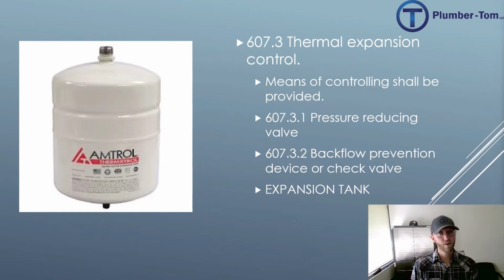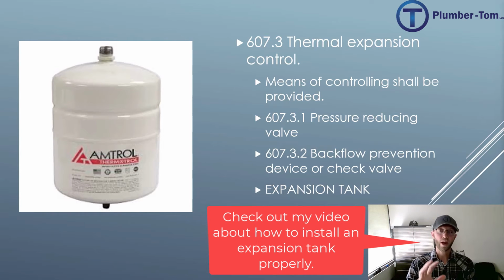If you're going to have hot water, you're going to have expansion. As water heats up, it expands. If it doesn't have anywhere to go, it drives the pressure of the system up. So the expansion tank is one option for handling thermal expansion. 607.3 requires that we do something to handle that expansion of water as it heats.